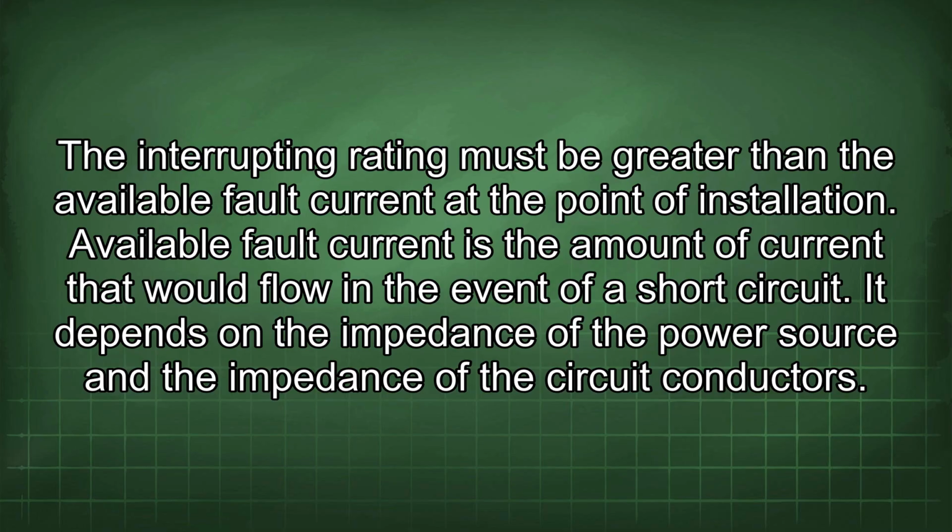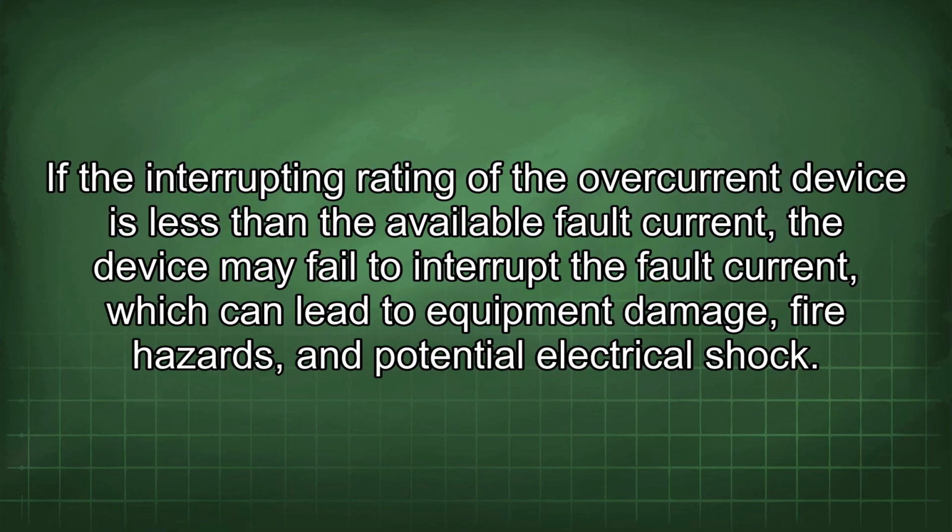It depends on the impedance of the power source and the impedance of the circuit conductors. If the interrupting rating of the overcurrent device is less than the available fault current, the device may fail to interrupt the fault current, which can lead to equipment damage, fire hazards, and potential electrical shock.